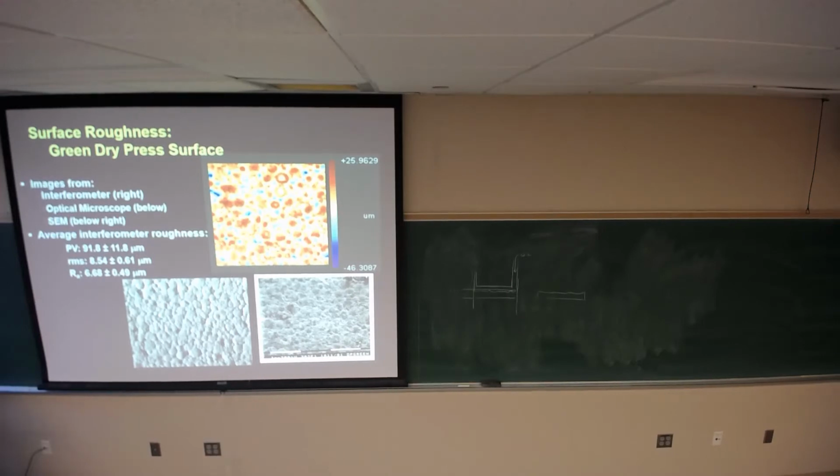Plus, they flip the tile over, comes out, and typically it's pressed so that the smooth faces down. And then when it's done pressing, it slides out onto the rollers and goes directly into a roller kiln, right? But usually what happens is sometime in there, it comes out, and then if they're going to do a print, they'll do the print online, but they'll take that tile and they invert it.